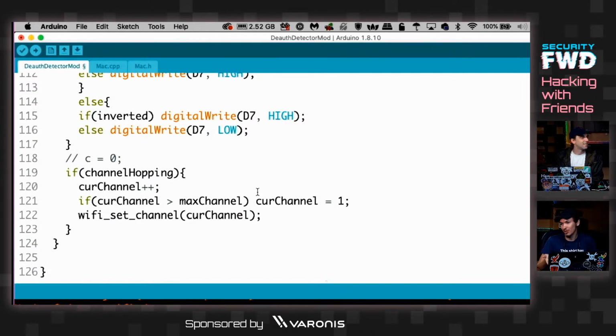The loop time itself won't change because the code's not changing. Yeah, so it's a very sneaky, ghetto way of getting around the fact that it's hard to call delays in Arduino when you're working with the wireless radio. You're welcome, guys. That's very sketchy, but a clever workaround, though still very sketch.